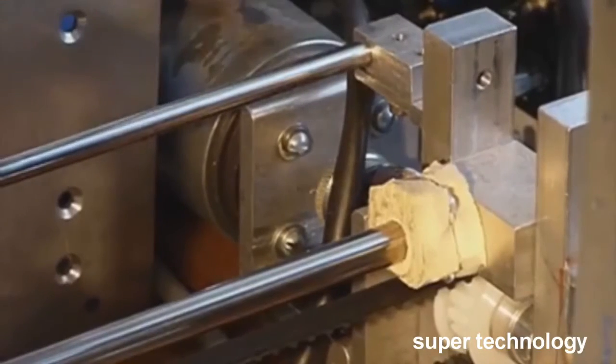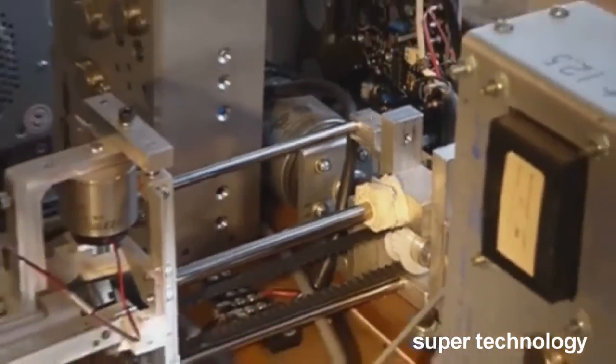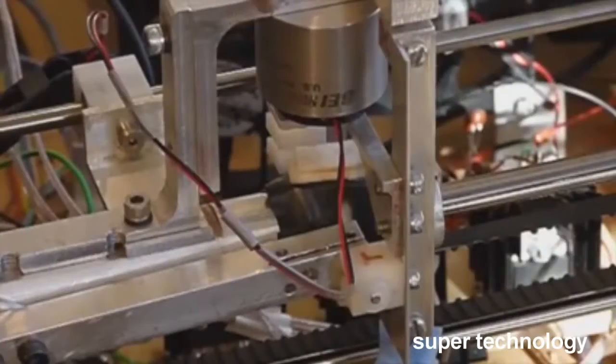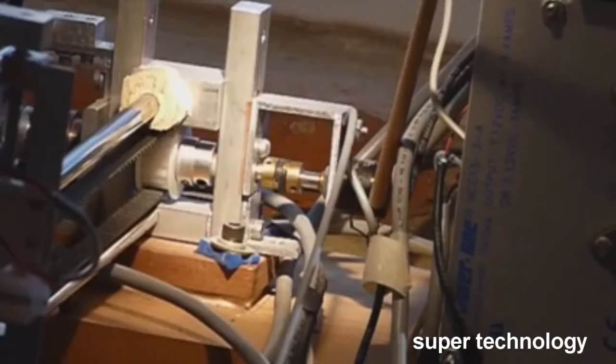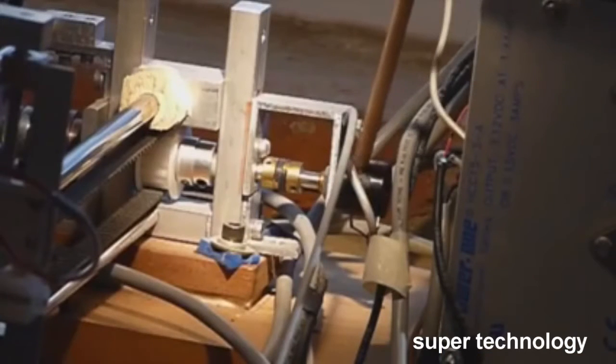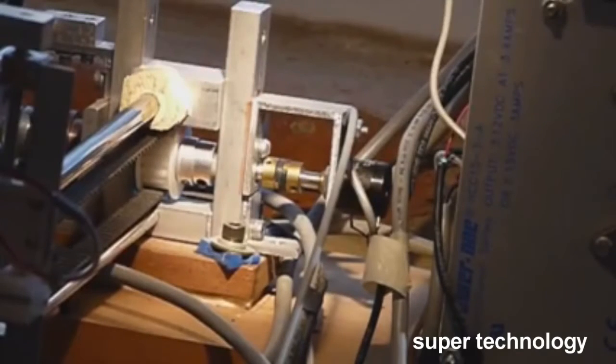The bow carriage is attached to the black tooth belt. The motor turns the pulley and that moves the belt and therefore the bow carriage. It has an electromagnetic actuator which moves the bow up and down. The black device attached to the pulley shaft generates a voltage used by the computer to reverse bow direction.